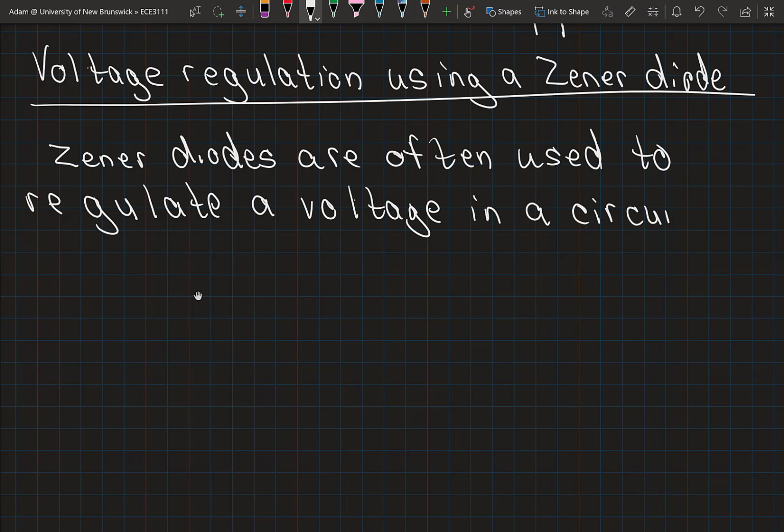Again, although they might be used, they're often integrated, and I'm not suggesting you go and buy a Zener diode to perform regulation. Get a device like a regulator or voltage reference, depending on what your application is.